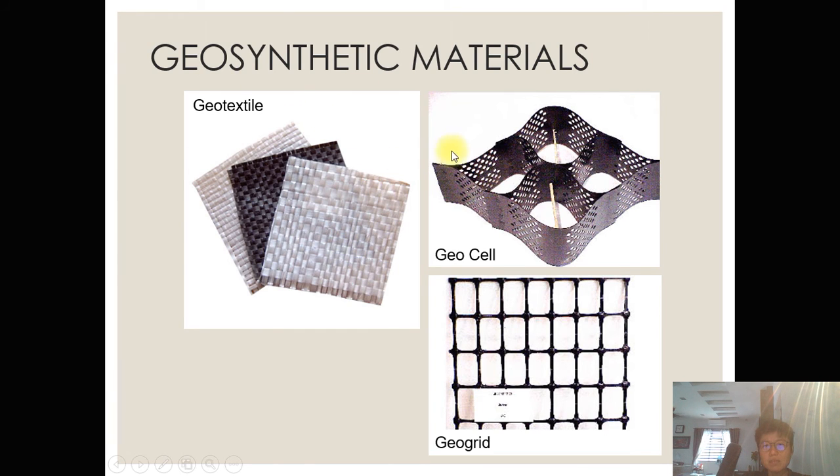These are geocells. It's not exactly new, but relatively new compared to the geotextile and geogrid. Geocell, can you see? It is actually collapsible, so when they deliver to site, it's easy. They just collapse it, piece by piece. And on site, they stretch it out and open it. So these are very much used where? You can imagine this is very much used in slope protection or slope stabilization on the surface, right? They have to excavate a little, put it in there, and then put the soil in, put the dowel in, keep them in place, and usually at the top of it, they do hydro-seeding. So over time, you have good plants growing over it, and you cannot see the geocell anymore.